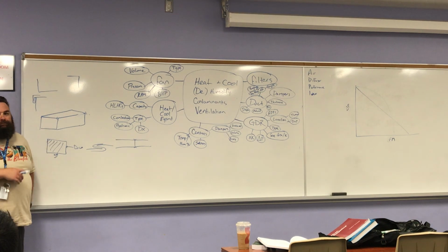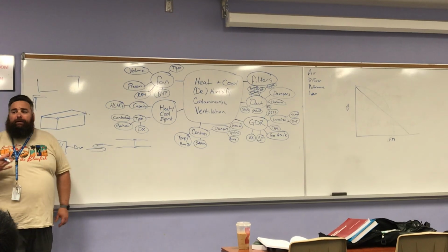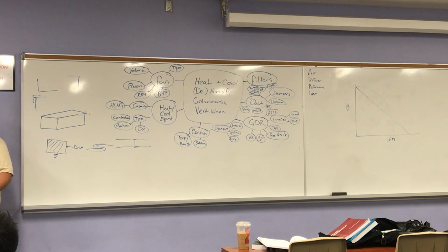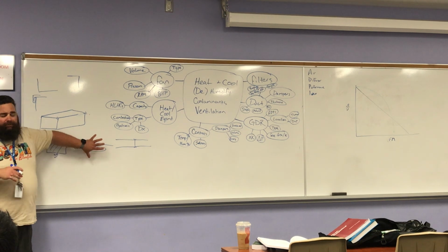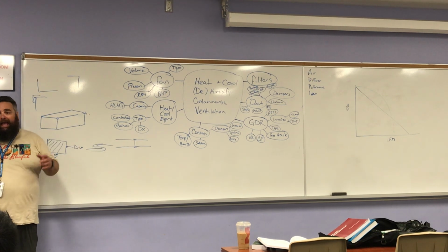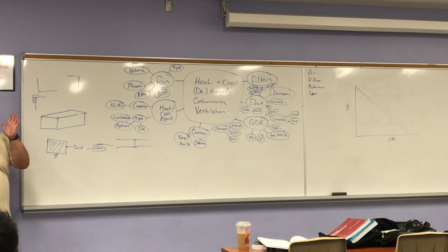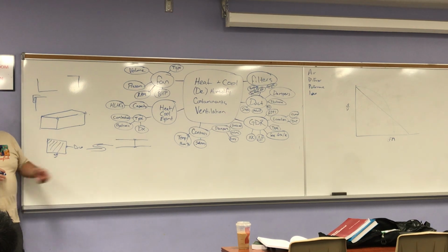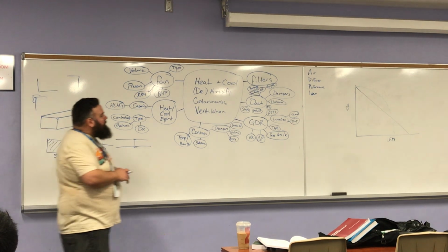Also very leaky and not very strong. When you get to higher pressure ducts or heavier ducts, now you have to have things like standing S, which is not just that S-shaped piece of metal, but also an angle incorporated into it. You might have flanged connections that have to be gasketed and bolted together. There's a lot of different connection types to consider. Okay?